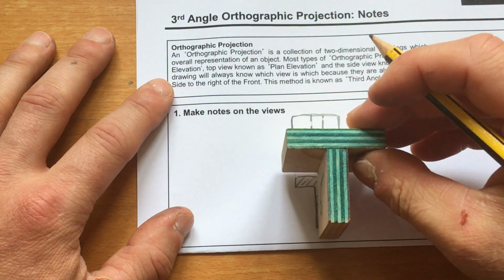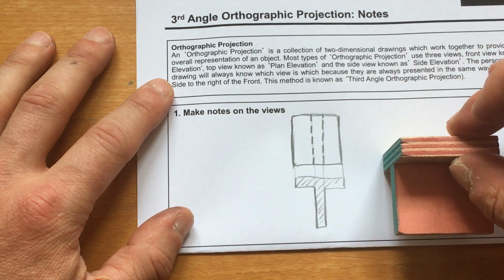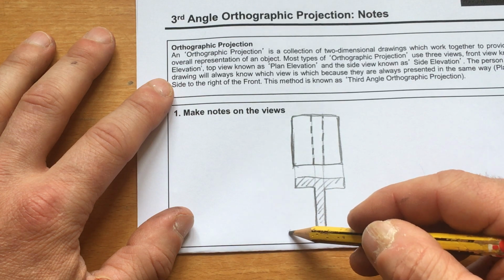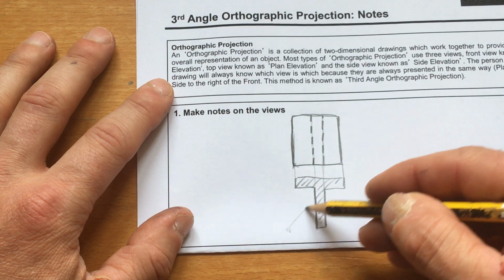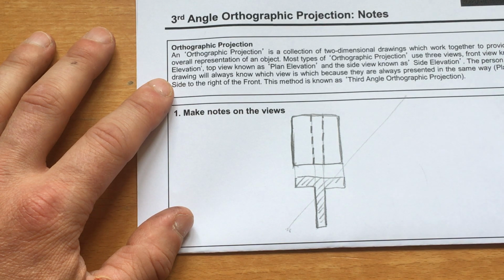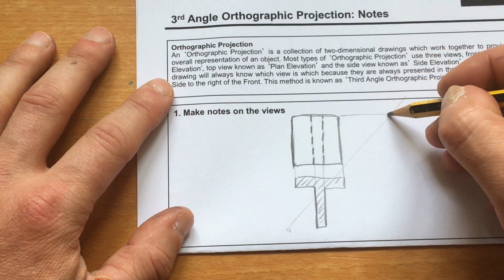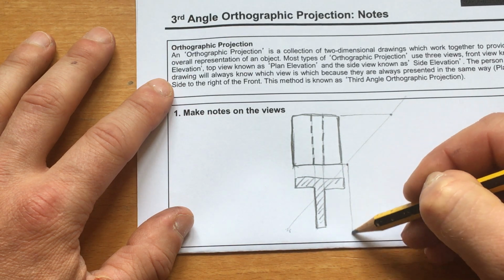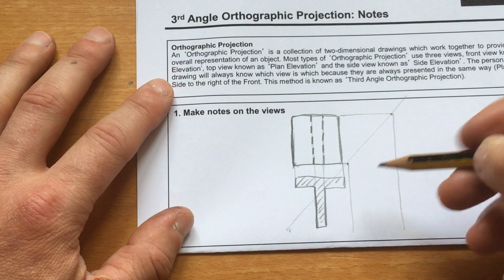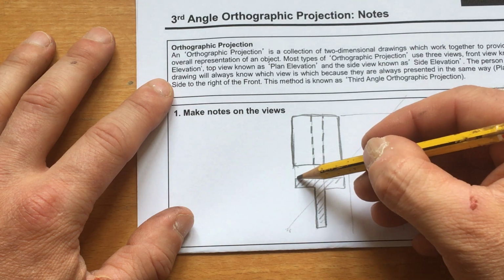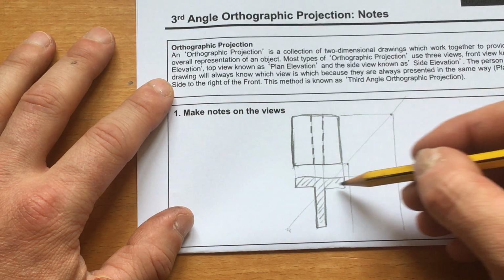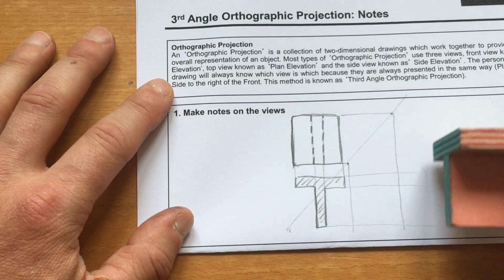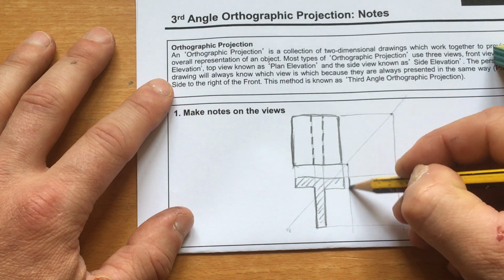What we then do is we take the view and then we move it to the side elevation here, but it can't just be anywhere, we can't determine that. So what we normally do is on the sheets we can just draw a 45-degree line across, or we can use a set square. We then project any horizontal lines which hit this 45, and as soon as they hit it, they come vertically downwards down here. Now here will be our side view, so what we then have to do is project across all our horizontals from the front view, go across here, and that should give us enough information to draw this side view, which is the red bit, and all we have to do is just draw that in.